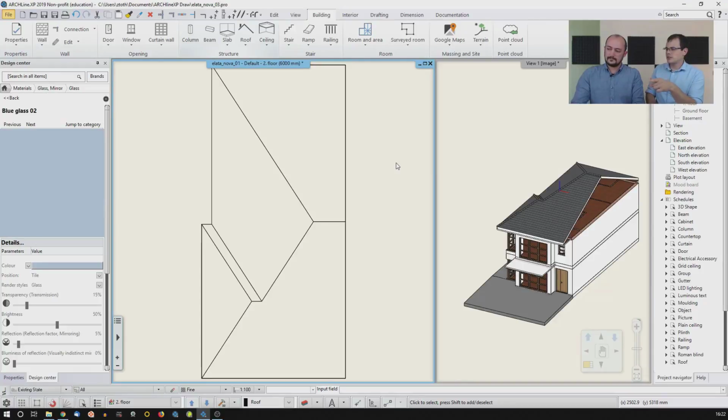About the firewall, this is going to be a very specialized shape, right? Yeah. This firewall, what we would like to create, is not under a roof, so we cannot make it cut with a roof, but it should follow the roof. So we need to use something which is a strong point of ARCHLine, the profiling of walls.